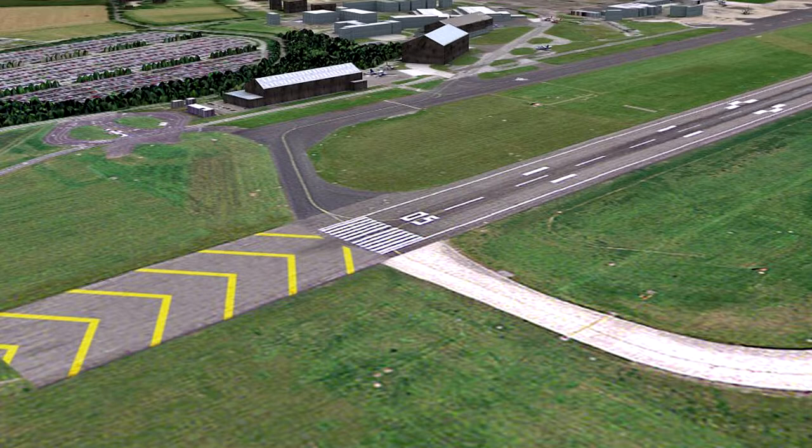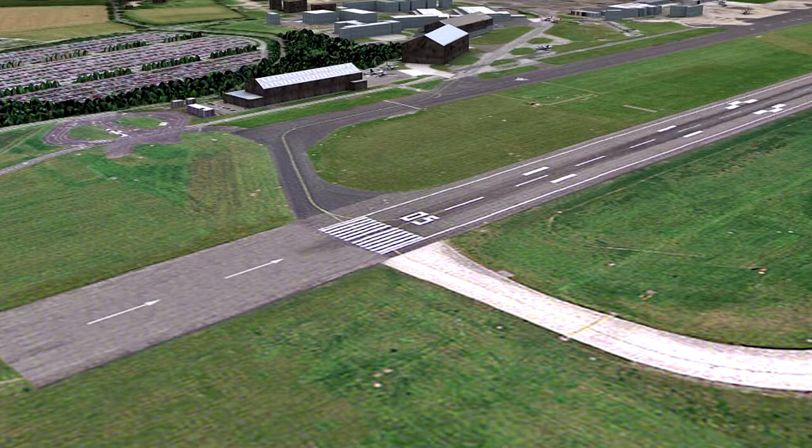As a rule, the takeoff or landing run should always be started or stopped at the threshold. There is one exception to this rule. If a pilot sees the runway markings shown here before the threshold, then he may use this marked portion of the runway for the initial takeoff run, but it must not be used for any other purpose.